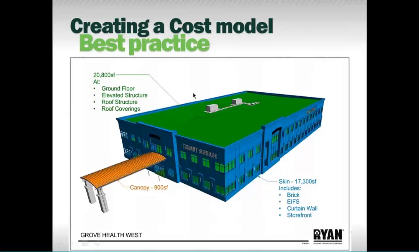You can start to notice the relationship between the skin area and this gross square footage. On smaller buildings, you'll usually have a higher aspect ratio, which is how much skin you have per square footage. The larger you get, you get more efficient in terms of you have more square footage for the amount of skin. But then the shape of the building, the number of floors, all those things play into that same dynamic. Again, the less skin you have for the square footage, the more efficient, and therefore the less cost you have.